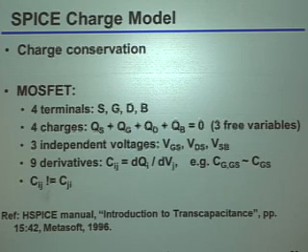So anybody ever wonder why the heck it is giving you both CGS and CSG? By the way, who's actually seen that? Okay, a few of you. So I strongly encourage you to run this exact experiment. You'll see there's probably way more capacitor entries in that table than you may have first expected.